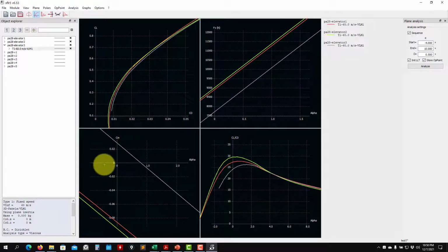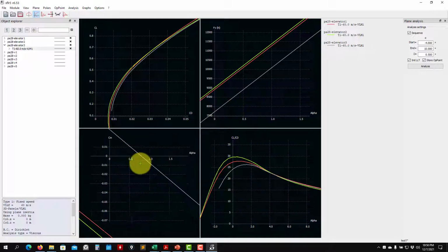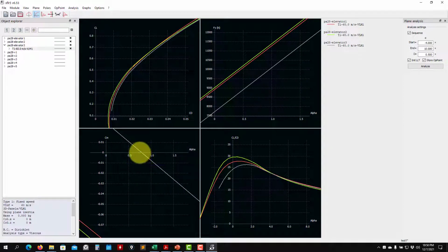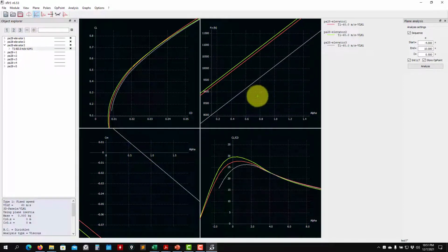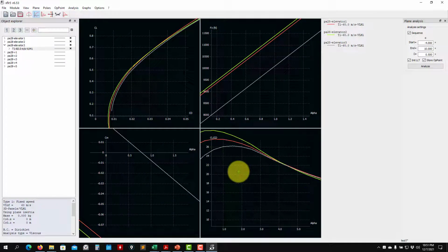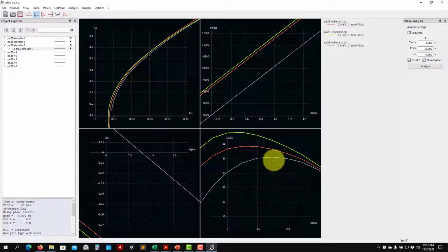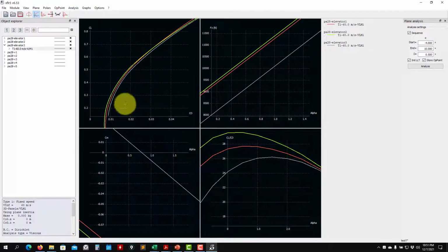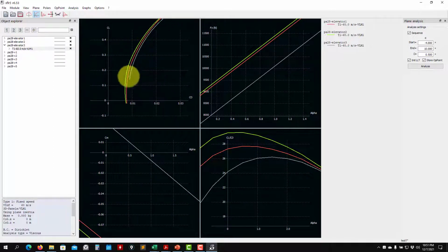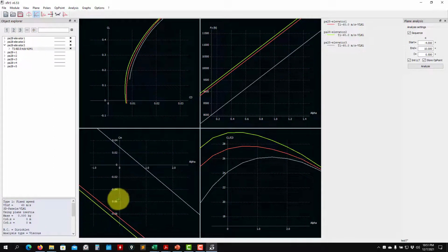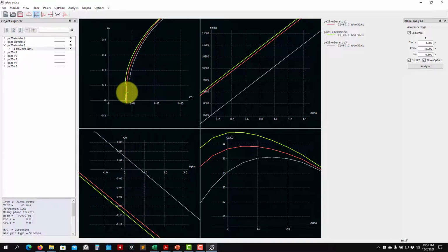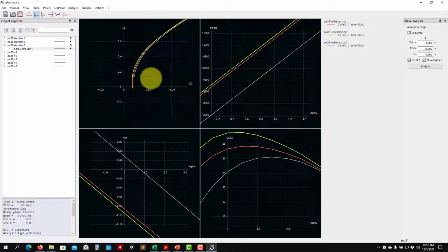Okay, so this is what we want, negative slope, and we want to find the trim. This curve must cut this line, the zero moment, very close to your cruise condition. So see that we have it here at 0.7, and our cruise condition will be something about 0.7. So this is already an optimal design. And if I look here, see that my maximum LD is very close to that one. Yes, I increase my drag, but there is no way. So the fact that I need to trim my airplane will increase the drag, but we want something balanced, okay?